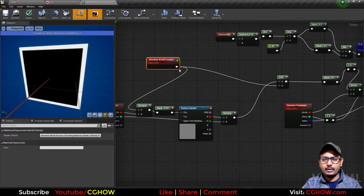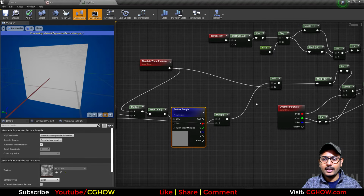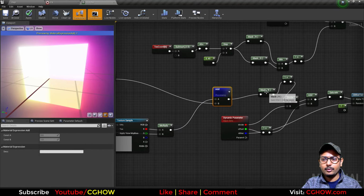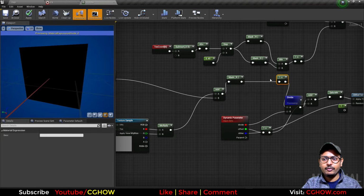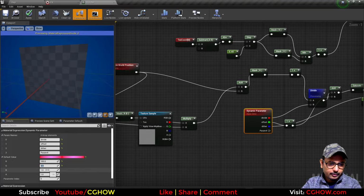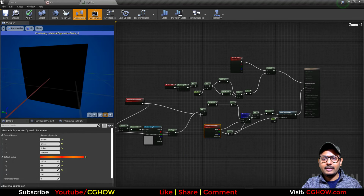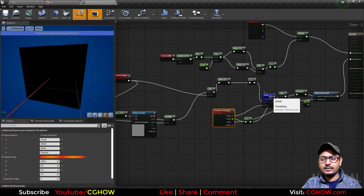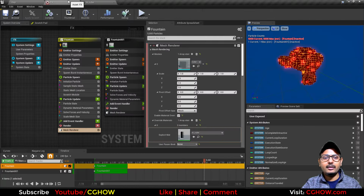Now here world position, and this is the noise that I'm using to distort that, then adding value on it, taking red channel, inverting it, dividing to fade it. Let me decide the value here, offset 0.5, dither 0. So same material, exact same material, nothing is different here. Just some numbers can be different in Niagara, but thing is same.